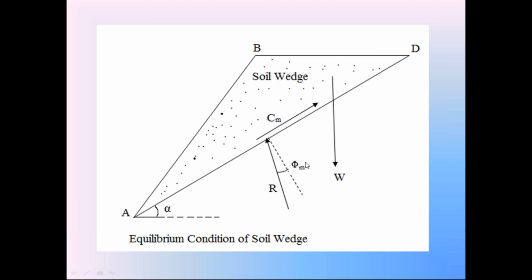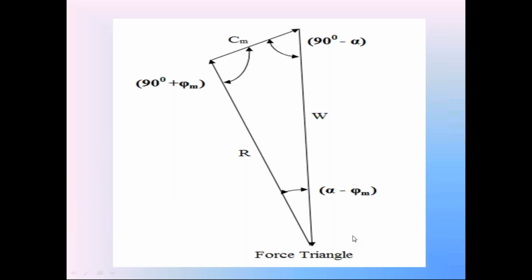It is also an unknown value, but you know this R is in the upward direction. Direction upwards, but we don't need to know this angle phi. So here in the force triangle, the procedure is very important. First, prepare this W vertically downwards according to some scale. Assume that, listen students carefully, this W is 100 kilonewton, acting vertically downwards.